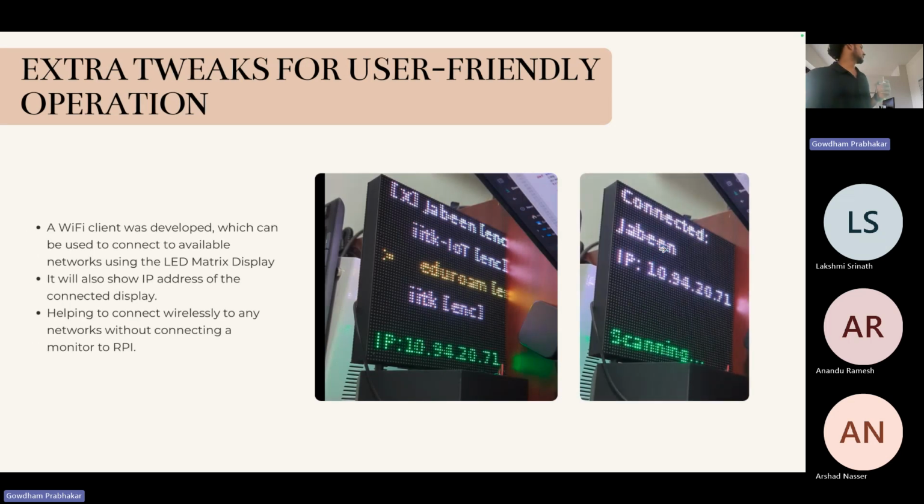After that, I thought we could connect the Raspberry Pi wirelessly with our laptop. But for that, we need to be on the same Wi-Fi network. And for connecting the Raspberry Pi to any Wi-Fi network, we also have to connect a monitor. To avoid that, since I had already provided a USB port above it, I thought to write code that lists the available Wi-Fi networks. So we can log into the Wi-Fi and easily get the wireless display here. So that's for the usability aspect.